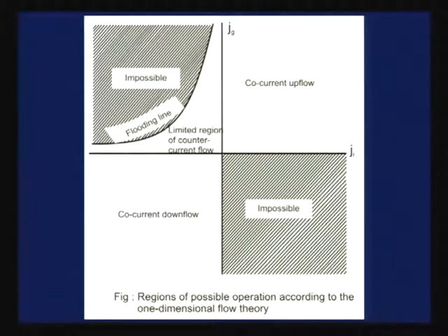Definitely we had expressed alpha, rho, T, p in local velocities in terms of the drift flux model. We found in all the cases the expressions that we obtained were a function of J21, non-dimensionalized or normalized with the individual volumetric fluxes. For all the terms we had J21 by J2 or J21 by J, something of that sort.